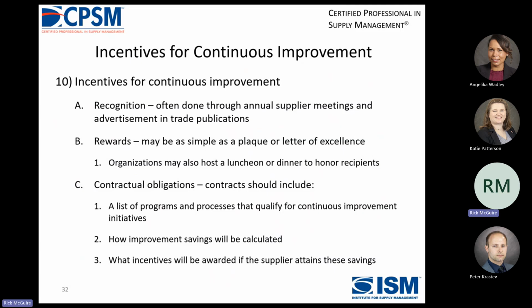But bear in mind, there are some processes that just are difficult to bring PPM down in. So if you're making an open mold fiberglass hood, it's all done by hand. If you get below 500 PPM, you're doing good. And like I said, on lift axles, you got like 1,500 opportunities for a defect on a lift axle, but still, you want them below 500.